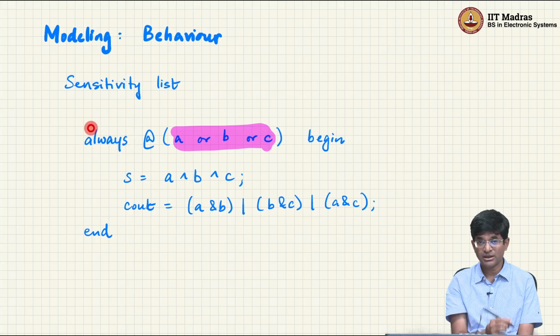block. Now an always block can be thought of as a separate chip of its own on a breadboard if you want to, right? You can almost think of an always block as a module by itself, which takes in certain inputs, performs certain computations and has a large number of outputs possibly, right? It's in general always possible to take out always blocks and create separate modules corresponding to each one of them, although it becomes a little bit clumsy after a while. It basically means that your code has too many variables or too many signals being passed around between different modules. You lose the power of the behavioral description that we would like to see, right?